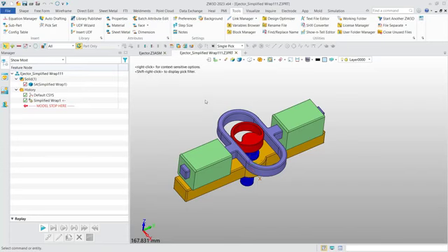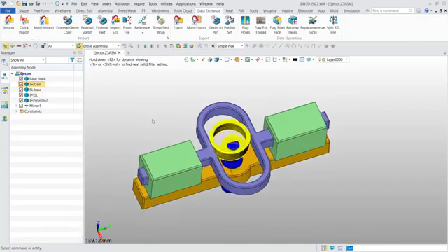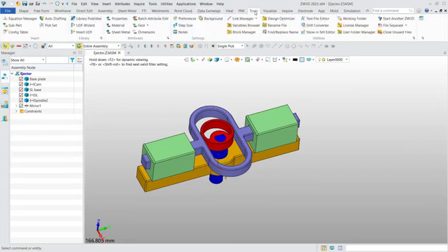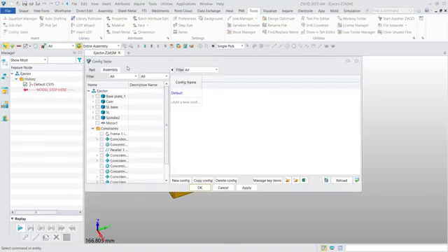And the last one is assembly publish. In the solid modeling tutorial, you already know how to publish a part. But the way is also available for assembly, and it's similar. Now let's see the difference. If we want to publish the assembly, we also go to the config table. And we can create assembly configs based on the component status or constraint status, and you can even create them by the part configs of the components.